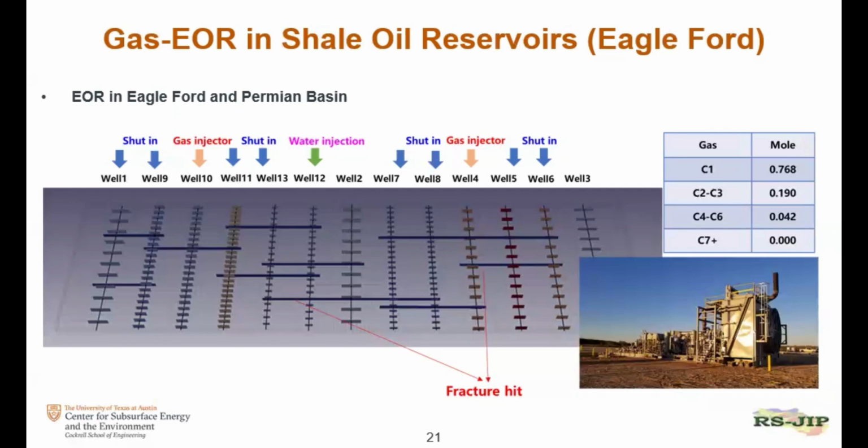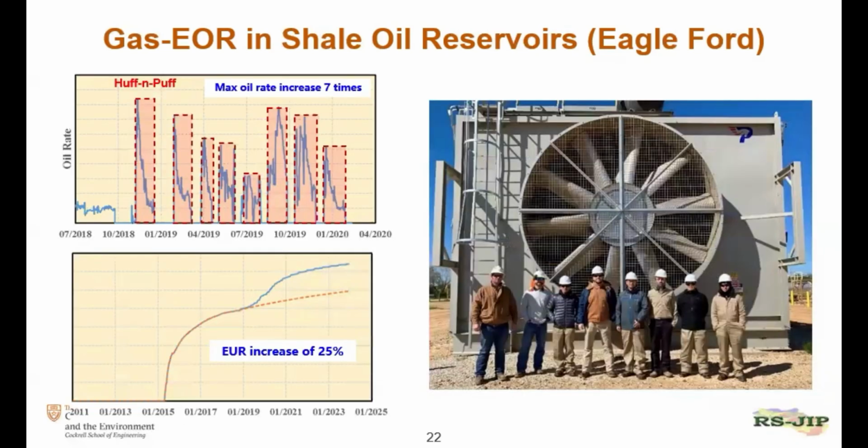And the thing I want to point out is that using the EDFM with the GPU reservoir simulation, we should be able to consider more wells, both laterally, horizontally, and vertically. So this is the incremental recovery from the EOR that we modeled. For this reservoir, we were able to get an EOR increase of more than 20% regarding the Eagle Ford gas EOR.